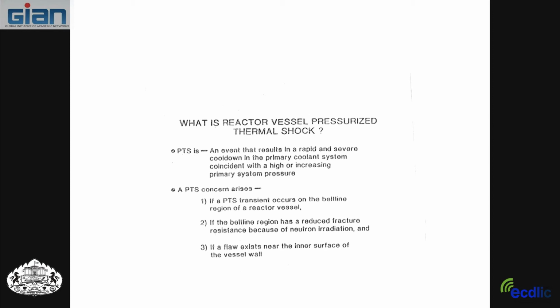I don't understand how the pressure builds up, but I understand the thermal shock. As you know, if you have a big wall, these walls are 10 inches or more, maybe 200-300 millimeters thick. And if you put cold on one side and hot on the other side, the cold wants to contract, the hot wants to expand, and that creates what's called thermal stress.